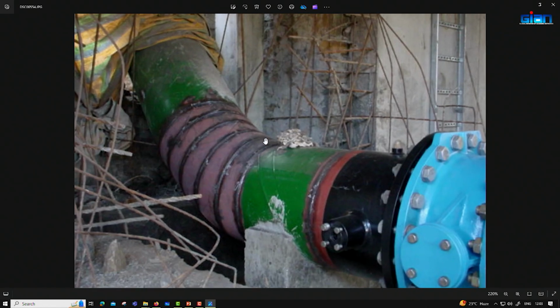Here they have done the smooth connection, you can see at the powerhouse entry. They have welded pipe pieces together to make a smooth finish, and then they will connect the flange here. At the powerhouse entry there is a big bend. This section will be completed with another anchor. You need to concrete this entire portion. From this point onward, all these areas will be an integral part of the powerhouse, and the anchor will be an integral part of the powerhouse.